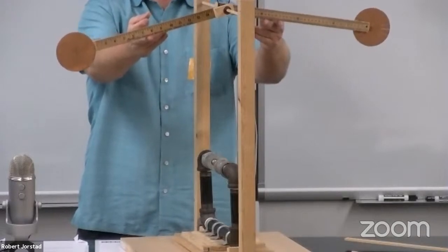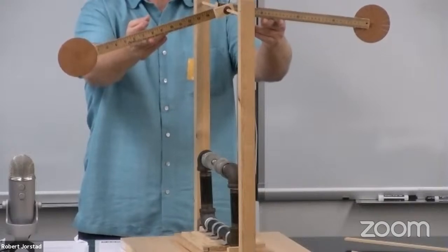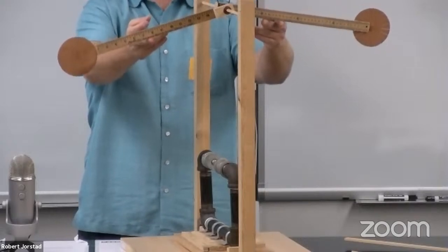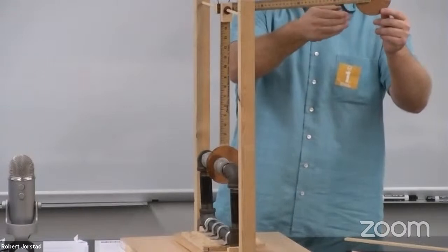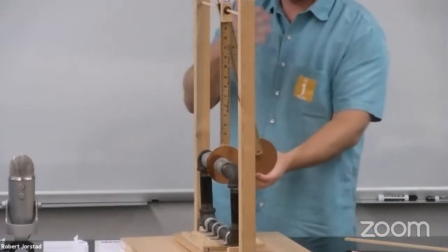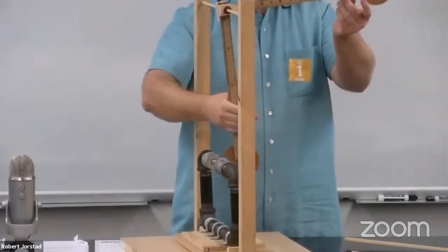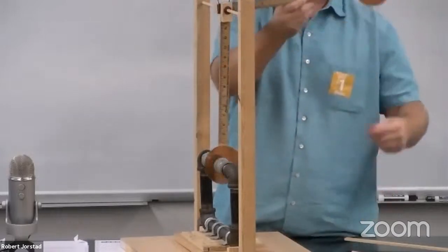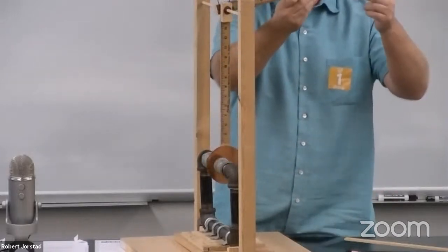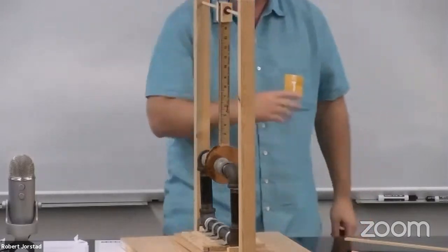Slits. What was the deal when we put a slit in the ring? No current, right? So the idea is the slits in this ring break up the eddy currents. All of these induced currents are sometimes called eddy currents, right? This one can have a huge eddy current because there's no slits. This one can only have very small ones. The slits basically break up the eddy currents, and so as a result, we see less magnetic braking.